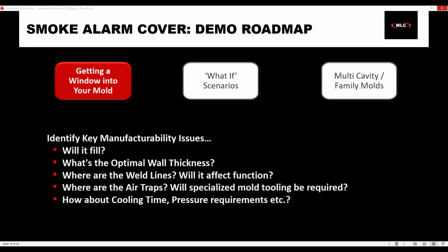If I wanted to see the weld lines, there's a nice little checkbox for that. And as we can see, there's this really long one here and on the other side as well. So there's some really big weld lines here, a larger one over here across the bottom, and then a bunch of small ones. We're never going to completely get rid of weld lines. You may always have a couple, but something like this is a little bit much.